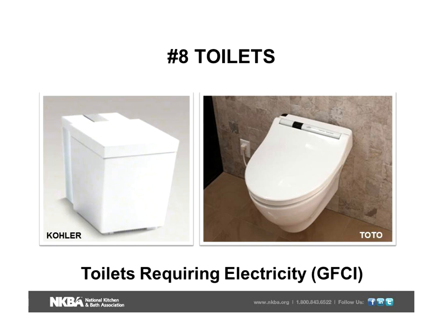Electricity. Who would think we need to check to have electricity near a toilet? This item by Kohler, a fairly new one, does require electricity for part of the flushing action. This Toto actually has a bidet attachment that requires electricity. So we are seeing, in fact, it's in our planning guidelines, it's not a bad idea to locate a receptacle near a toilet.